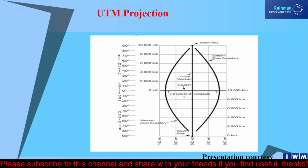And see, this equator line is considered as 10,000 kilometers, so that we neglect the negative value of northing. And this is my North Pole and South Pole. This is the central meridian line, and this is the equator line, and this is the part of the globe. We have just cut the globe at 6 degrees and fit it on the plane surface.